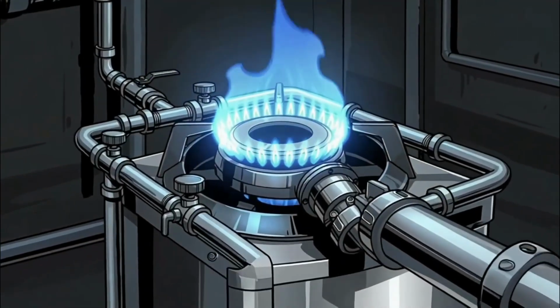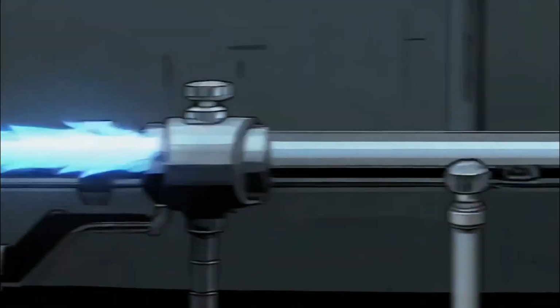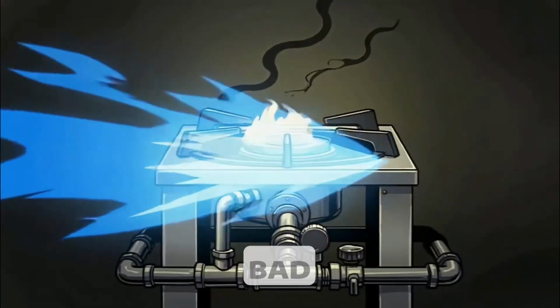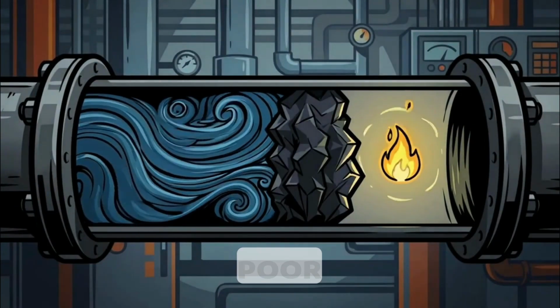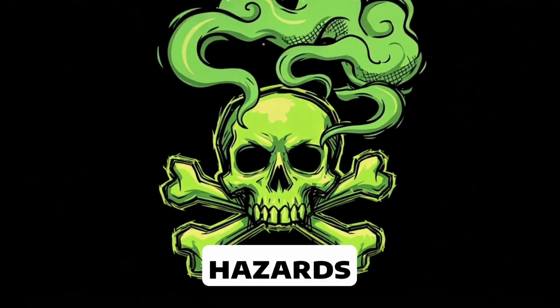Now, burners. The burner mixes gas and air and burns safely. A proper flame should be blue, stable, and well-defined. A bad flame may be yellow, lazy, lifting, floating, or sooting. Yellow flame often means incomplete combustion or poor air supply. That can lead to carbon monoxide hazards.